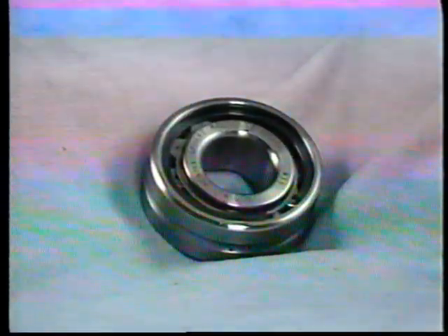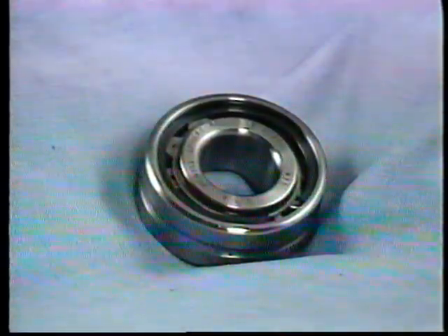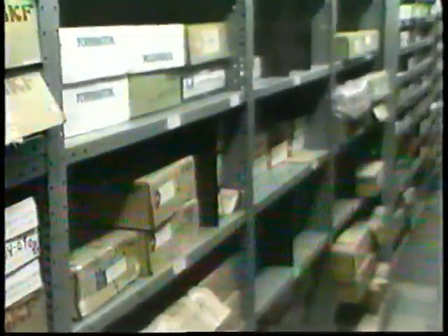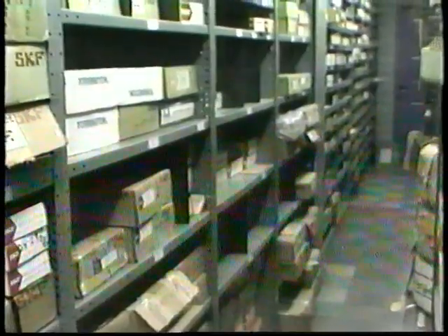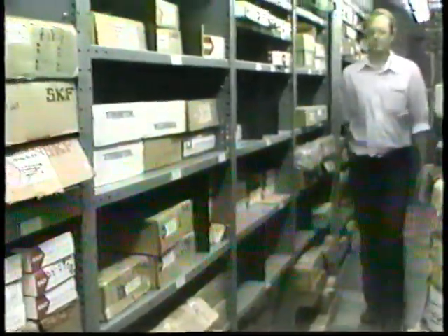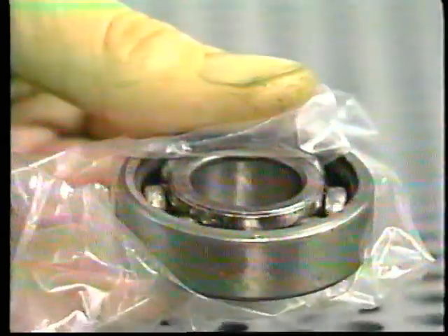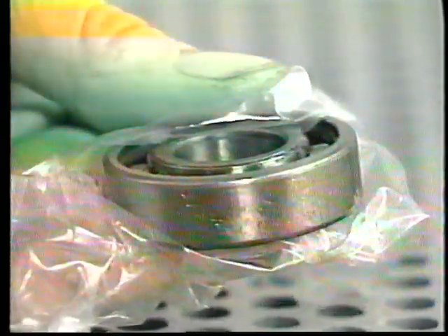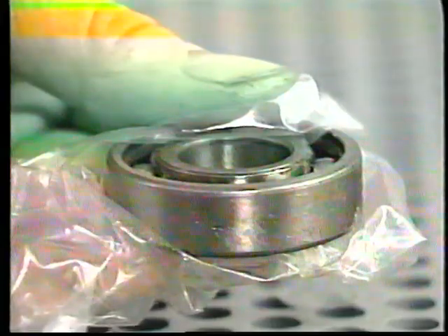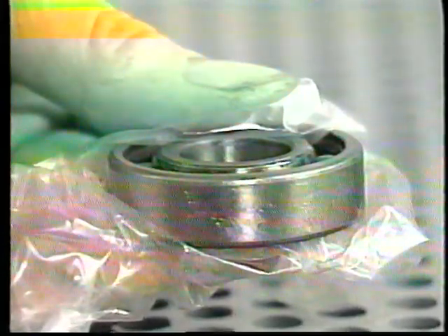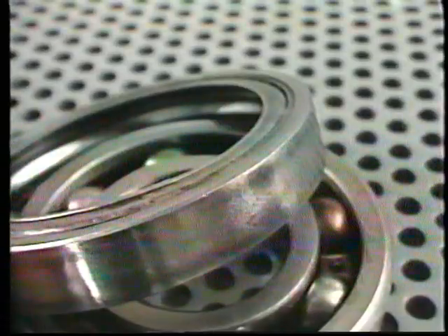Occasionally, a bearing will fail due to damage that occurred even before it was installed. Bearings should not be stored in areas subject to dampness, vibration, magnetization, or extreme changes in temperature. New bearings should be kept wrapped and in their original box until you're ready to install them. New bearings should not be handled more than is absolutely necessary. They are coated with a protective film to prevent rust and corrosion. Do not remove this coating or store bearings dry, that is, without the protective film.